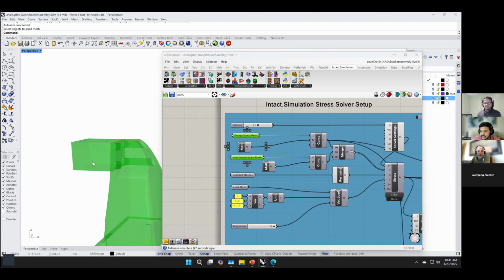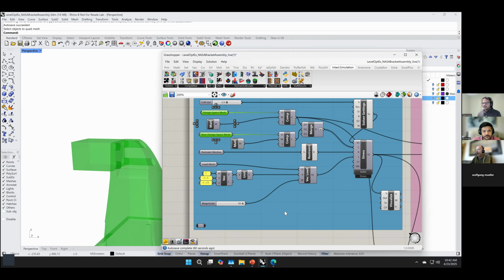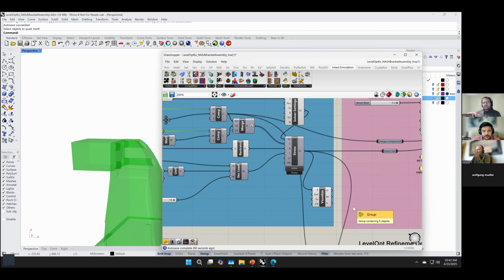Julian has asked, is it possible to add material in stressed regions with a positive volume fraction constraint? That's kind of like the starting design that you showed. So if you go with a starting design and your design domain is larger, but you removed material from your starting design where it was needed, and you allowed the design domain to be large enough to add material, it will add material in that region as well.